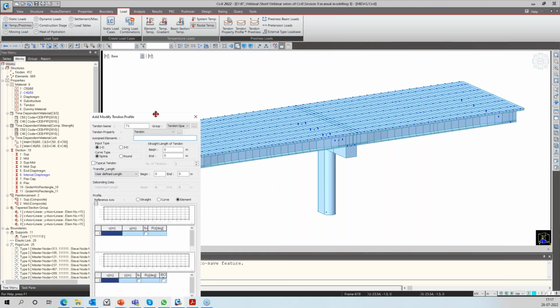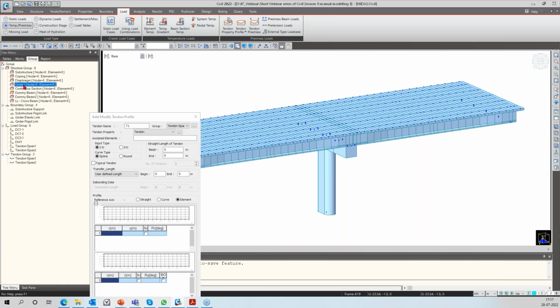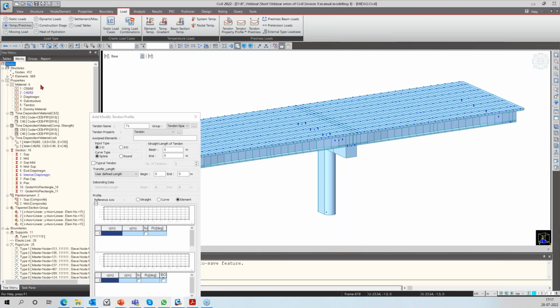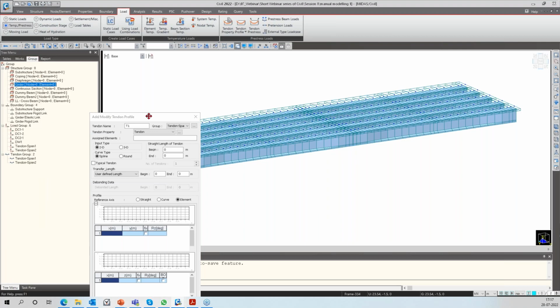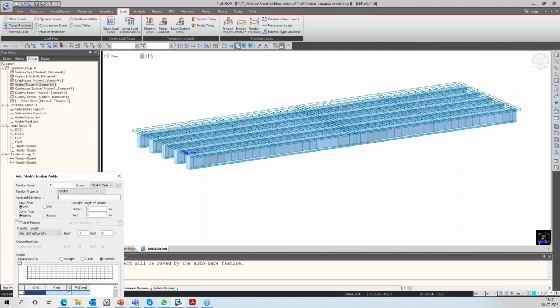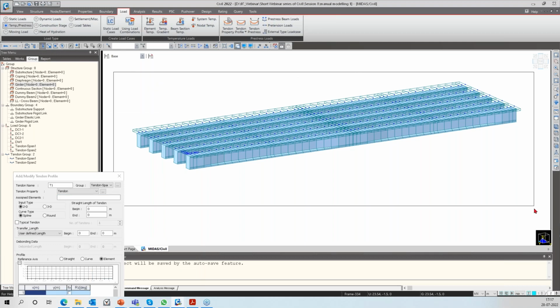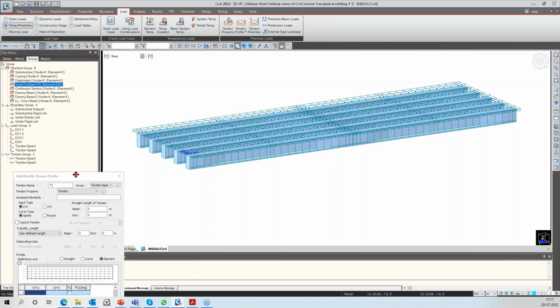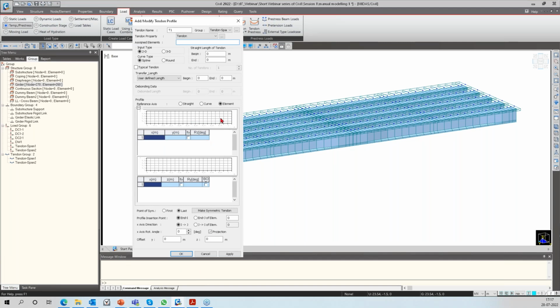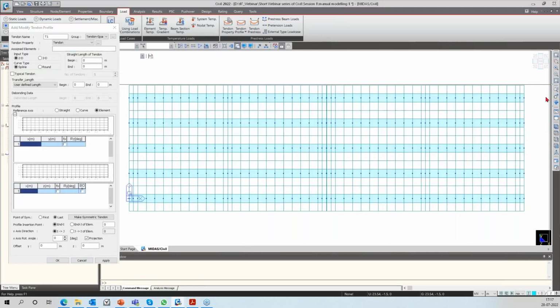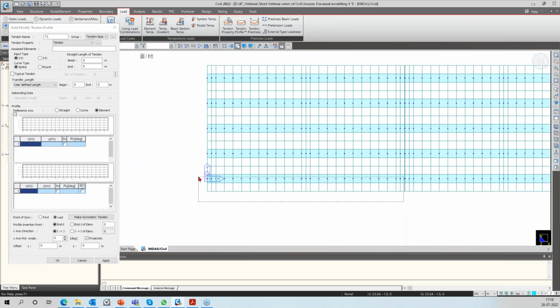and what the assigned elements are. Now to assign the elements, let us activate the girders. So we will select the girders with the help of section properties. Here we have some section properties, just select them, right click and say active. We can put them under the girder group so that it is easy for us to select and also to put them under a certain construction sequence. So yes, we have our girders over here. Let us do the selection of our elements.